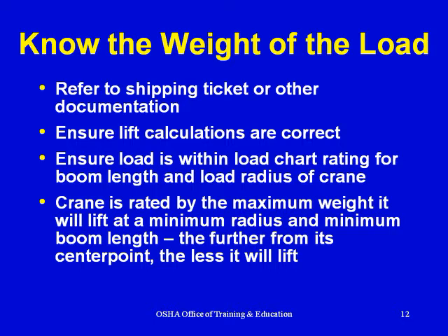Ensure lift calculations are correct. Ensure load is within load chart rating for boom length and load radius of crane. Crane is rated by the maximum weight it will lift at a minimum radius and minimum boom length. The further from its center point, the less it will lift.